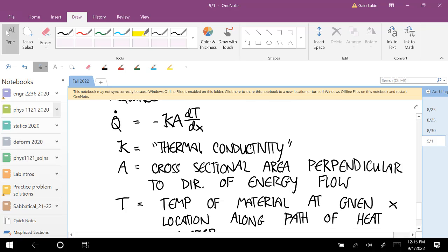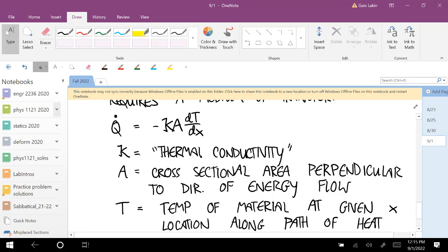Okay, so if you have a very steep gradient in temperature, you have a much bigger heat flow. That window is not very thick. If our side of that window is 70 degrees Fahrenheit and the other side is 65 degrees Fahrenheit, then the rate of heat transfer is pretty small. If our side is 70 and it's negative 40, then that's a really steep temperature gradient, and so we have a real high rate of heat transfer. That makes sense.